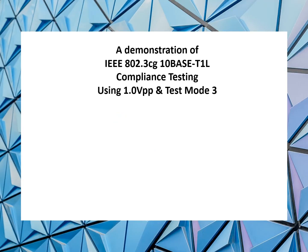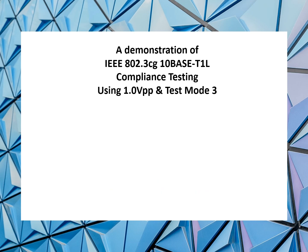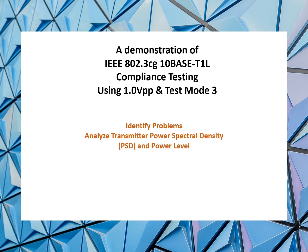Welcome to a demonstration of IEEE 802.3cg 10BASE-T1L compliance testing using 1.0 volts peak-to-peak and test mode 3. This demonstration will feature the Analog Devices evaluation board and Ethernet PHY evaluation software with Telebyte's digital analyzer, probe, and software. This demonstration will show you how to identify problems, analyze transmitter power spectral density and power level, perform repeatable testing, see clear pass-fail results, and produce printed reports and graphs.